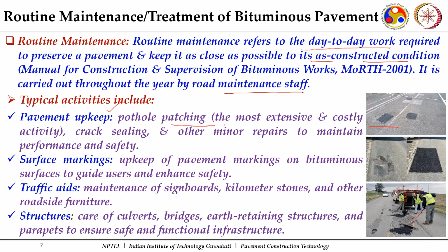So, that particular pothole patching has to be done immediately, because it may intensify your distress, may damage the nearby pavement structure, and may further deteriorate your pavement structure. So that is why one important aspect is to work out where any pothole patching is required.